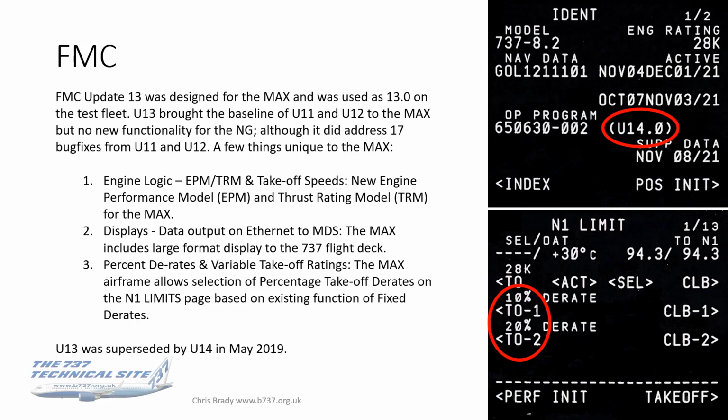The third one is probably the most interesting, or arguably the only one interesting to us as pilots, and this is percentage derates and variable takeoff ratings, and I've highlighted that on the lower photo there. They're actually writing 10% and 20% derate, which is what takeoff 1 and takeoff 2 used to be.